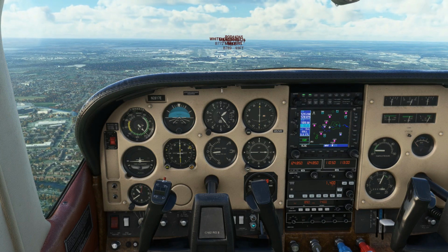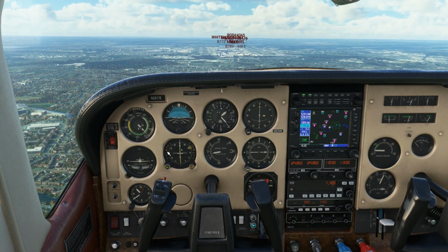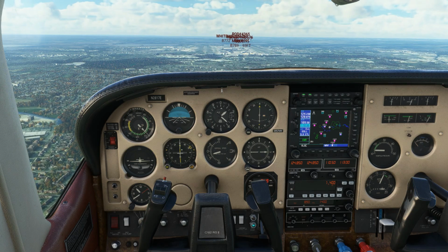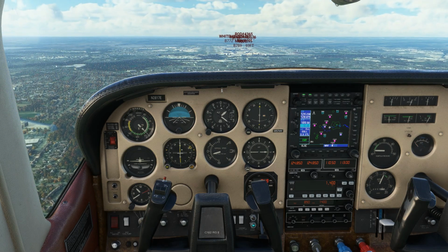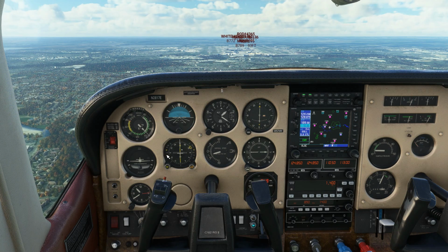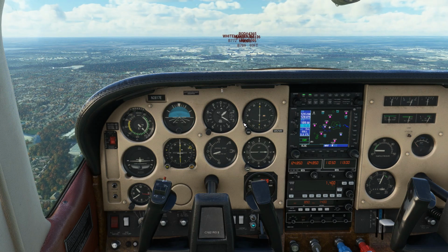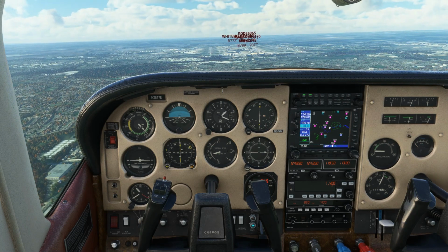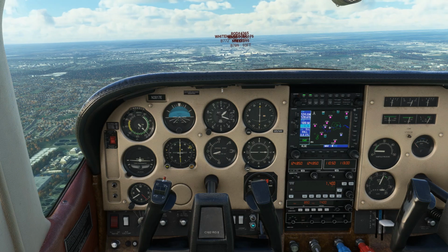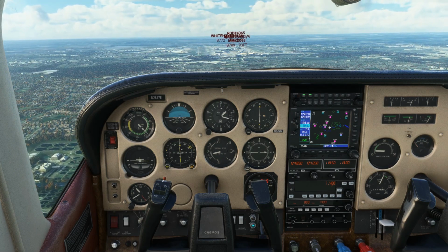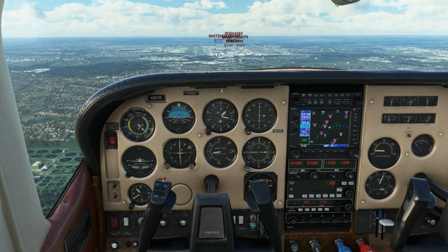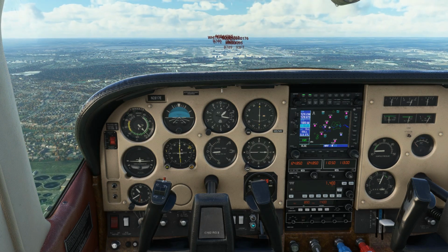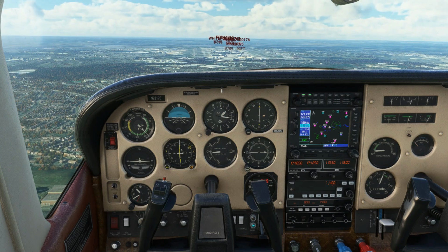Go to the second stage. Now I can see these indicators moving down. It's no longer under autopilot control. I've got control, and I'm going to try and keep these indicators in the center. I've got the runway right in front of me, so I've got a visual representation of the runway. I'll soon be able to see the PAPI lights as well, so they'll guide me in. Two red, two white, so I'll probably pay more attention to them whilst glancing at my instruments. Probably best I did take it off autopilot so I could show you this in practice.